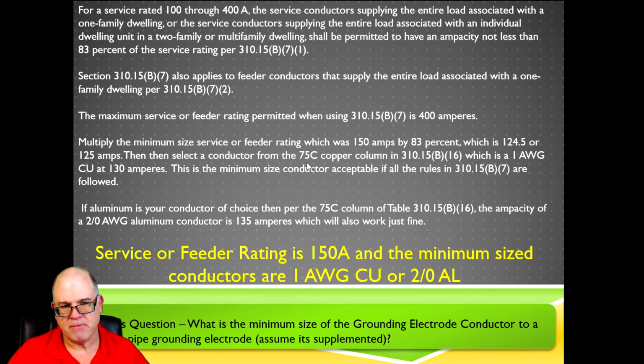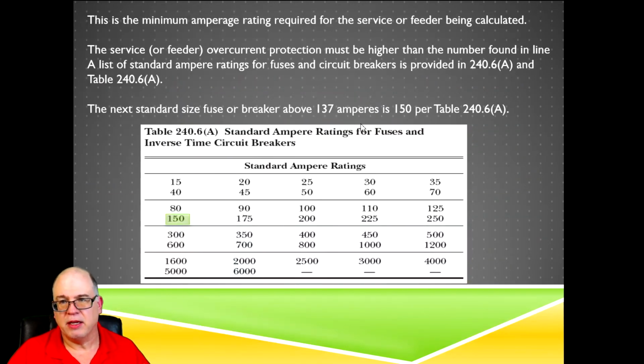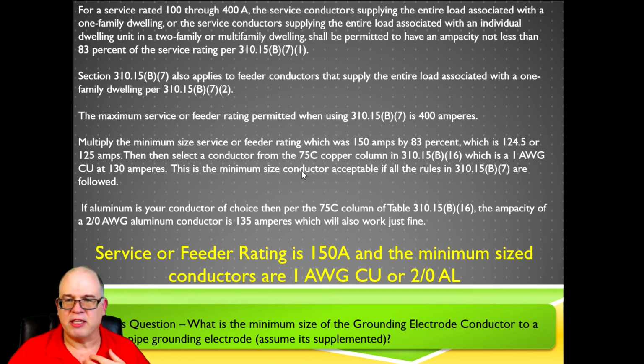All right. Remember what we were at, and we couldn't find when it corresponded, so that's why we ended up going up. And I think if we go back, it was right here. Okay. We had 137 amps that didn't correspond, so we go to there. Here, we are saying that it's perfectly okay, per the code, to have a 125 amp rated conductor and it terminate on a 150 amp device.